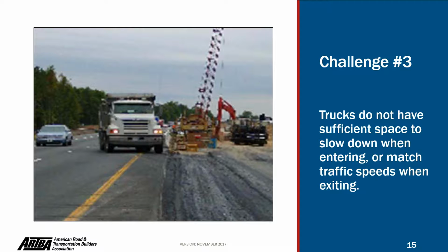Okay, so think about a dump truck arriving to a work zone in which the soil is not going to be pavement but regular dirt. So the brakes are not going to work the same. And think about it, if it was raining, it's going to be worse, or if it was snowing or black ice and all these things. So we need to provide a ramp for these vehicles when they arrive.